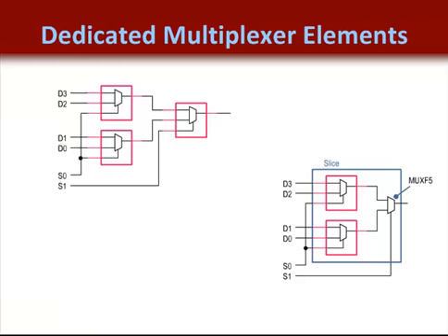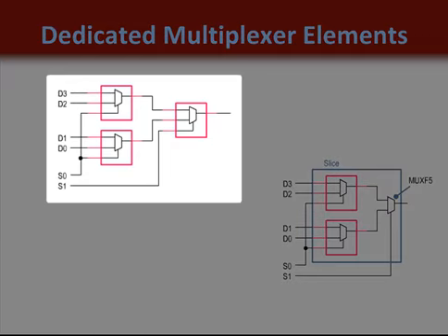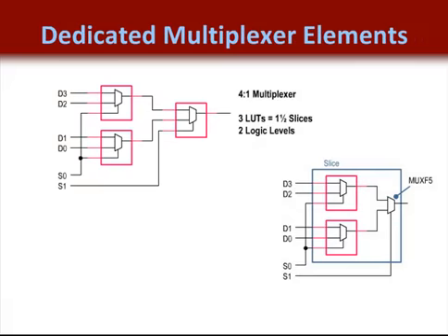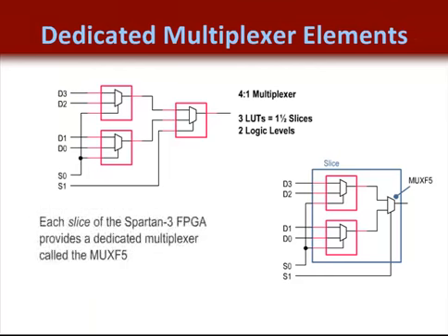As this slide shows you, originally, when you built a 4-to-1 MUX in an older device family, the MUX was built entirely of just the lookup tables. In this case, a 4-to-1 MUX would use 3 LUTs and be built with 2 logic levels. Pretty good performance, but as you make the MUX larger, the delays will increase quickly, and you'll end up with multiple logic levels and hence slow performance.